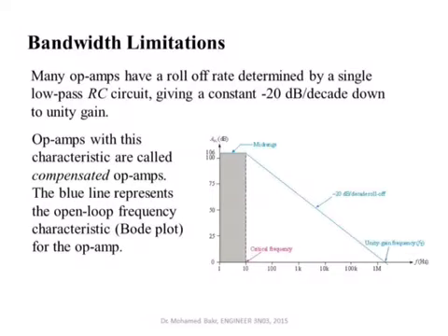One other thing to remember about an OpAmp is that the OpAmp itself really supplies a very high gain over a certain bandwidth, but gradually and slowly this gain starts to decay, and it goes from 10 to the power 6 up to only a gain of 1, say beyond 1 megahertz. So just remember that an OpAmp will act as an ideal amplifier only within a certain bandwidth, but its very high gain starts to decay gradually and slowly as the frequency of the input signal is increasing, until we reach a certain frequency.